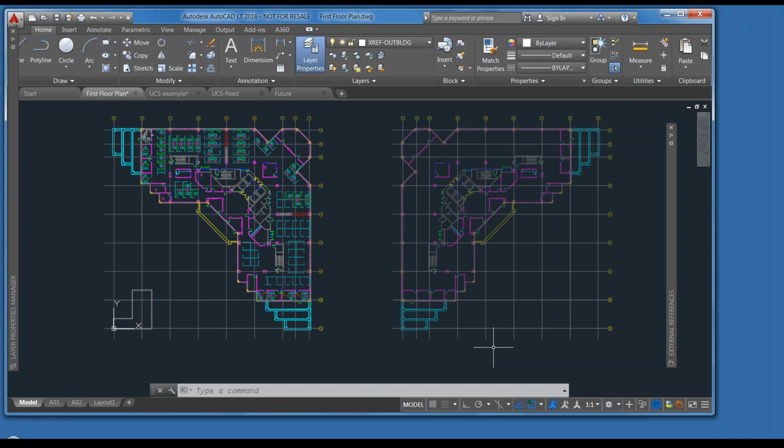Another tip that is easy to overlook is because this takes so much work, so much setup, let's say you're ready to start a new drawing. Maybe you even have another phase of the project where there's a connection between these two buildings. So do you have to go to a brand new empty template drawing and start from scratch and pull everything together? Well, one shortcut might be to do a save as, which is the equivalent of just copying this drawing.